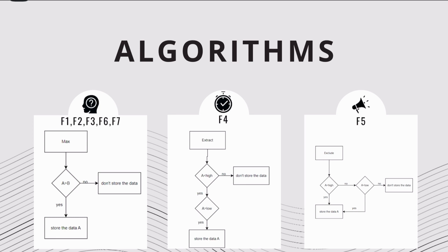Firstly, let's discuss the algorithm. Given that the core functionality primarily involves comparators, we aim to make the core function of the main module similar in order to minimize the area usage. Functions 1 and 2 involve finding the maximum and minimum value among each set of 8 numbers.